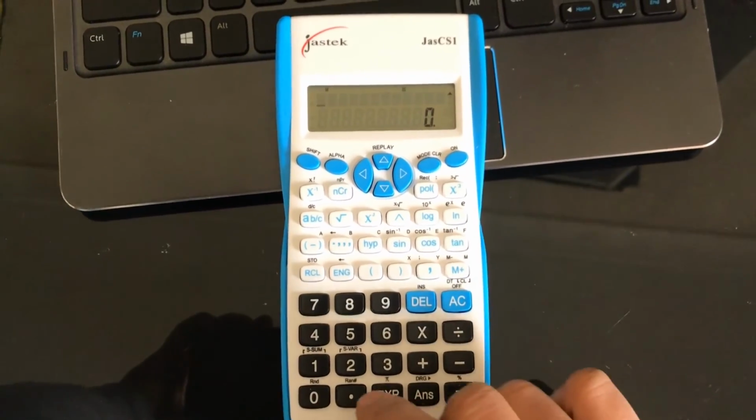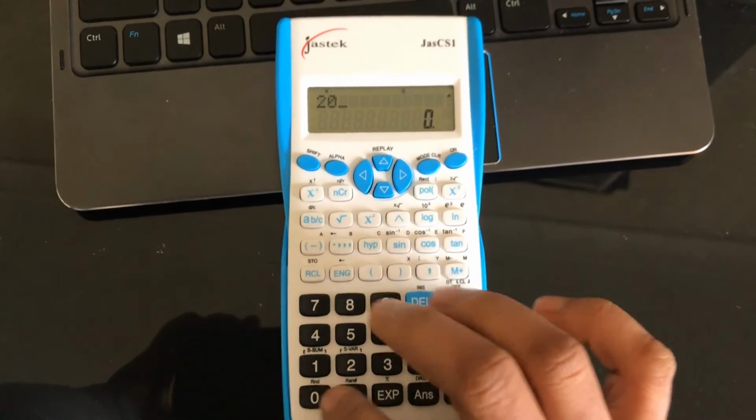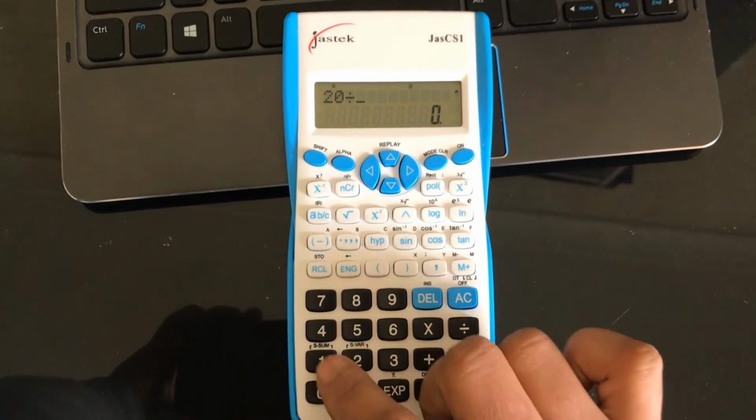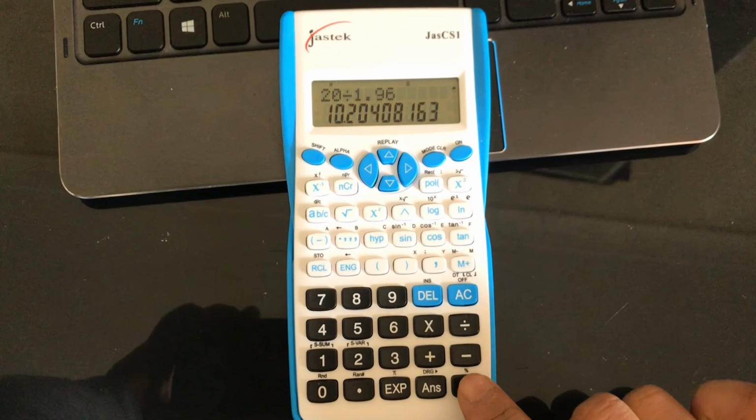Now I picked up a value from the graph paper, the last one, 20 volt and 1.96 milliampere, and then I'm calculating like this, and I can find out the resistance: 20 divided by 1.96, and it is 10.2 kilo ohm. So this value is nearly the manufacturer value, and we found that from our practical test result.